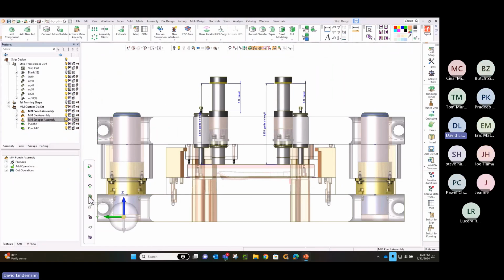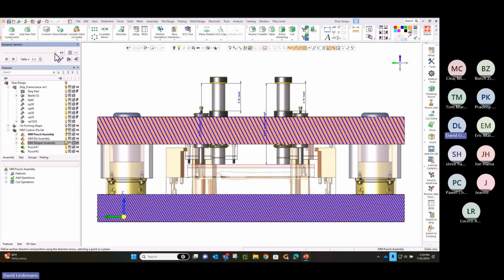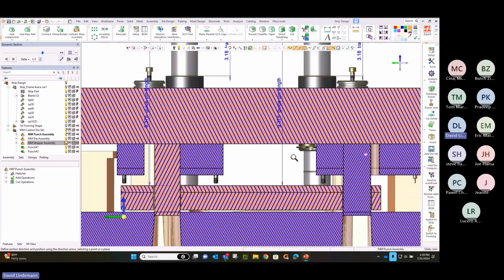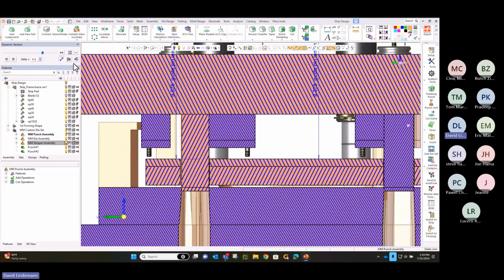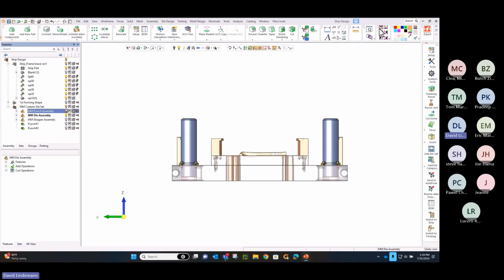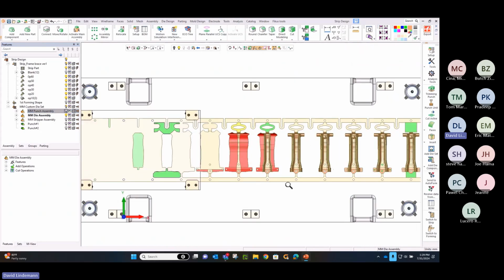Side view, you can see how it built the clearance for the coil where my plate is coming down on top of it. You can see the clearances it's built for the movement of the plate going between the material guide. And then there in section, you could see the punch as it cut through all the different holes. So naturally, if there's a change, we just update those punches if I were to reorder them or if the shape were to change.